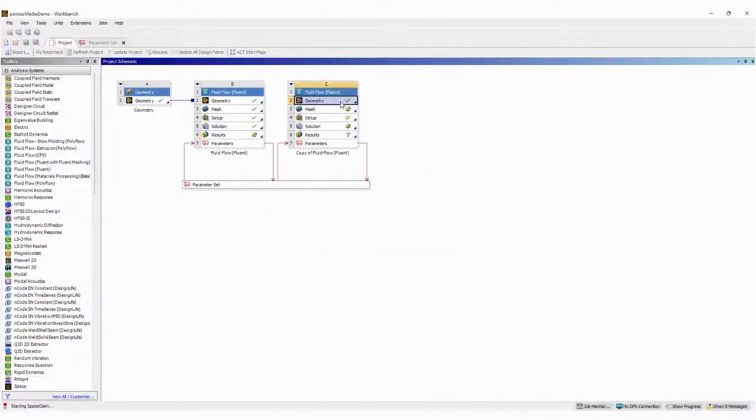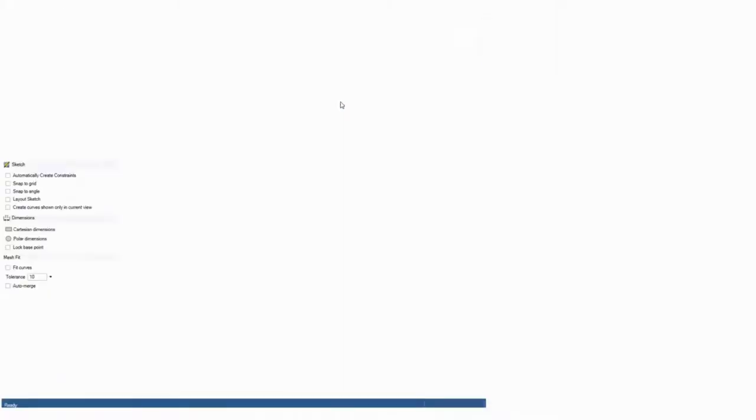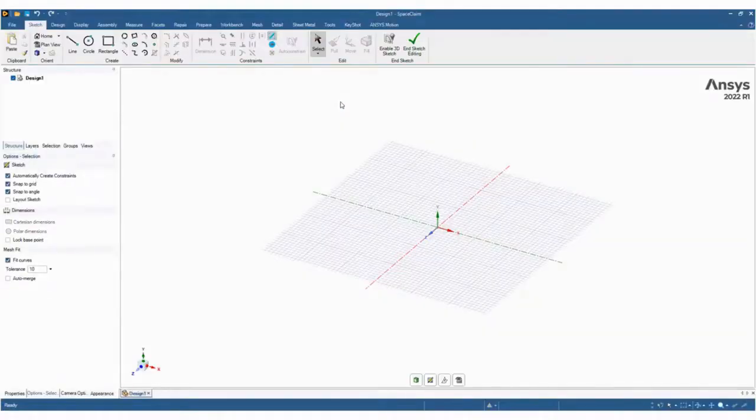And we'll regenerate the mesh, the geometry here. We'll model the area in between the two as a porous media in between the two air sides. We'll remodel our grill as a porous media zone. Run the simulation and see if we get the same results.